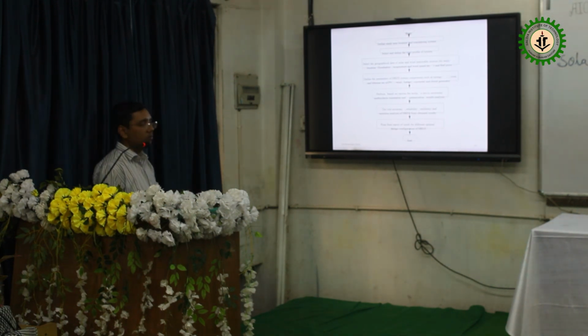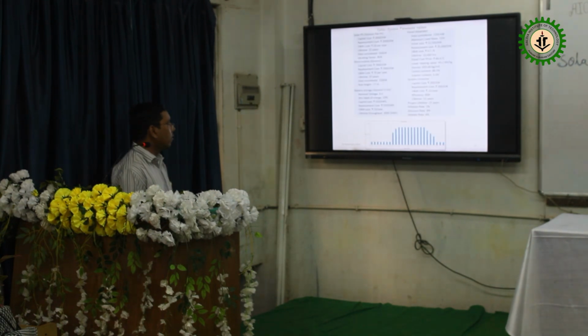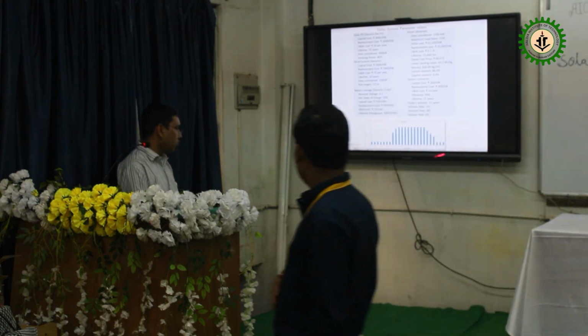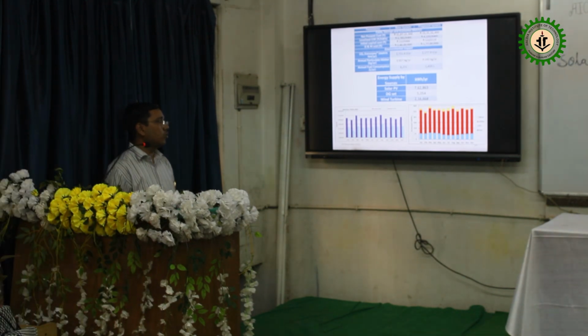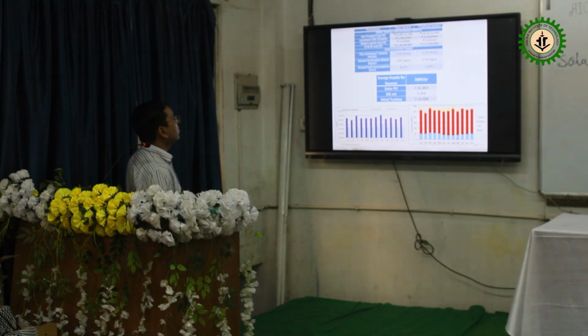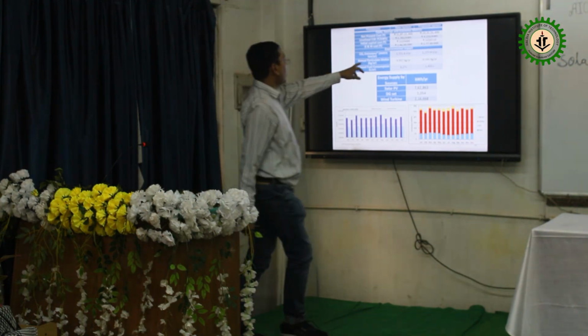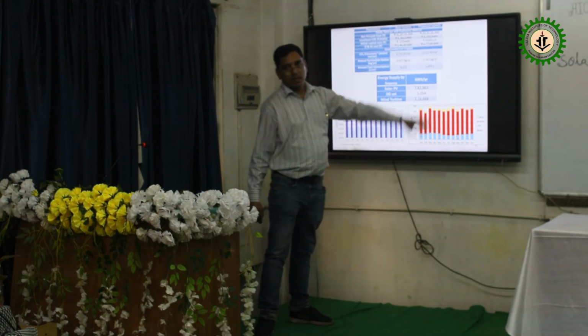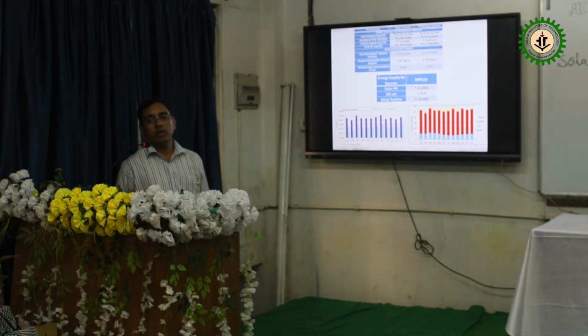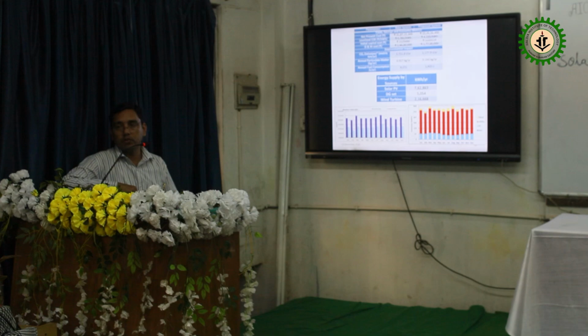After that, for different conditions you can do the analysis. Based on this electrical case study I have done for these parameters, sample parameters I am giving here, and this load profile, I have looked at the output and the cost of energy. Earlier it was 5.78 when taking from the DISCOM power. After installing the panels, it comes to 4.2 per unit, and it will consume maybe 5,000 units per year. Then you see what the economic impact is, the saving here.